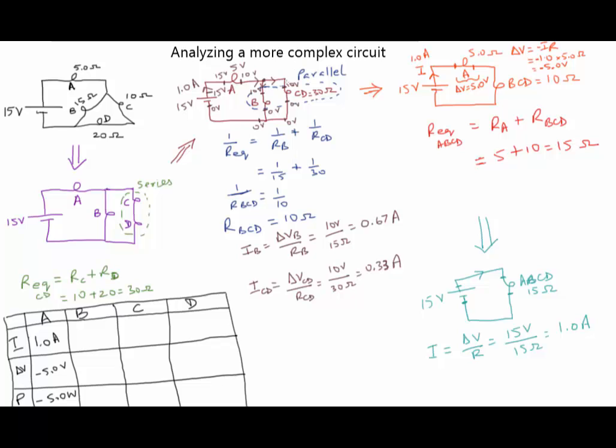And it's useful whenever you get a chance to verify these simple laws to make sure that there is no math mistake you made in doing these calculations. So let's see what all we have gained to fill into our final answer bucket over here. So for the resistance B, we know the current through it is 0.67 amps. We know the potential drop across it in the direction of flow of current is 10 volts, so just write it as minus 10 volts to follow our convention.